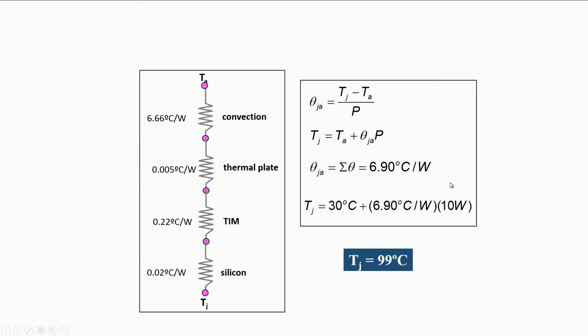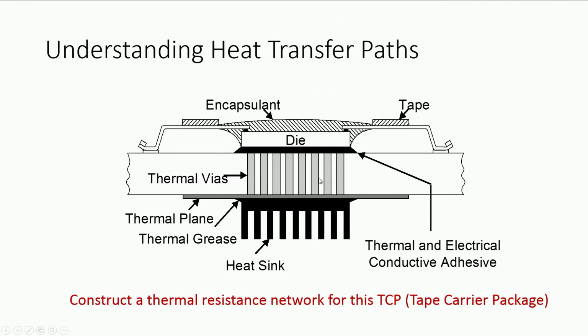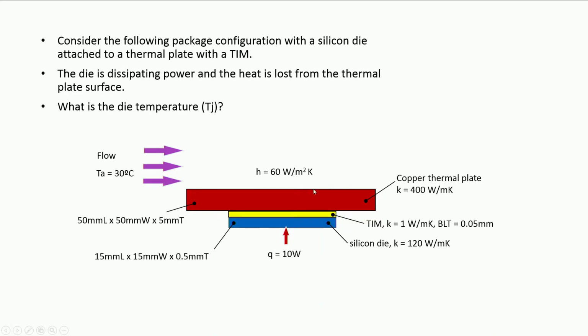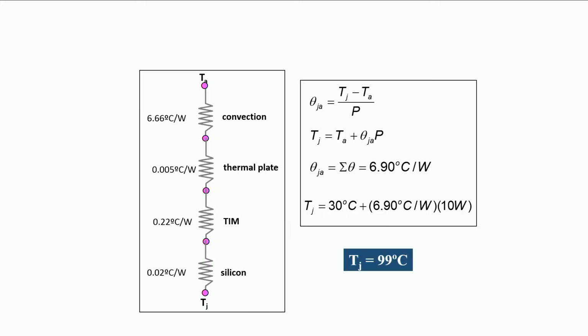So that is where we have to focus. Finally, I am going to focus my attention on how to improve, or rather reduce, this case to ambient thermal resistance. That should be my focus as thermal engineers, not on something which is not going to give me a lot of return on investment.